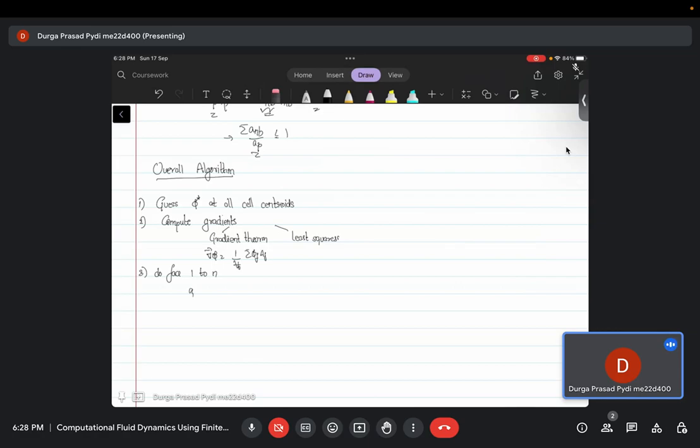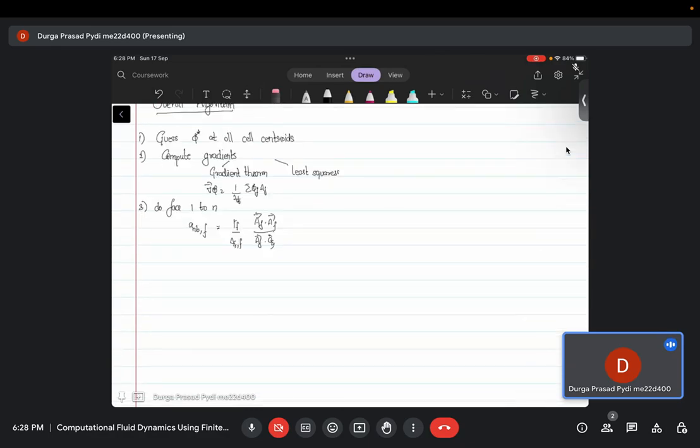What do we calculate? We calculate the value of A and B. You know this as A_f dot A_f by A_f dot e_zeta cap, and then we can calculate the value with respect to the particular cell, the corresponding face, as A and B_f, and for the neighboring cell, the next cell, it will be minus. You just need to multiply it appropriately, and secondly we need to update the secondary gradients along that particular face, and from there we will add that secondary gradient to the existing value of the B0 term, and this has to be done for both the cells.